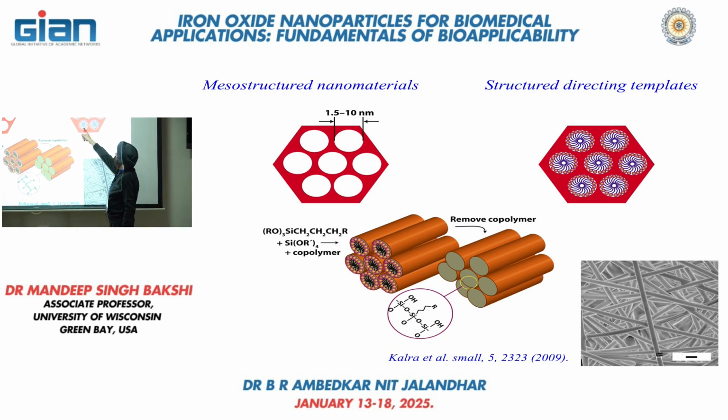Carbon is going to burn away, right, or decompose. So the micelles are going to decompose, and as a result you are left with simply this template of silicon oxide. This is the way we grow it. This is one way of creating the templated structure of silicon oxide, and we can use it for some purposes. So I'm going to talk about that as well.